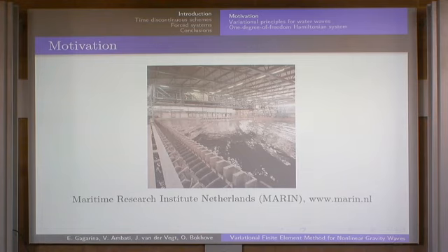Nevertheless, to test it, you need to know exactly what kind of sea state you are interested in. So generally it's possible to do an inverse problem and then define how you should move the wave maker. Nevertheless, the opposite is also useful. It's useful to have a computational method which will create a so-called numerical wave tank. So a wave tank with a moving boundary.